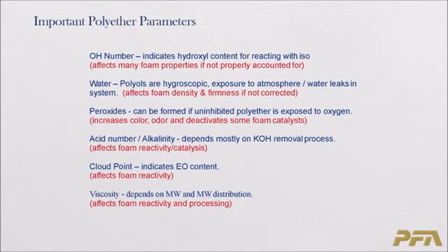And they are also susceptible to oxidation. Again, why you keep them under a nitrogen blanket, so that you're not forming peroxides or any color bodies or odor type materials that can affect reactivity or foam performance. Again, if you're dealing with a KOH polyol, you need to worry about is there any acidity or alkalinity remaining in the product, and also you need to know the viscosity of that polyol, because it will affect your mixing capability when you go into production.